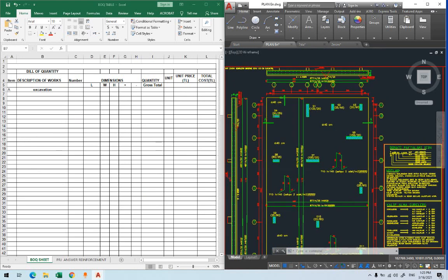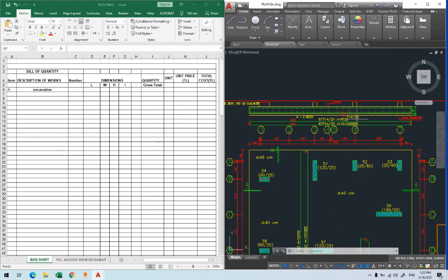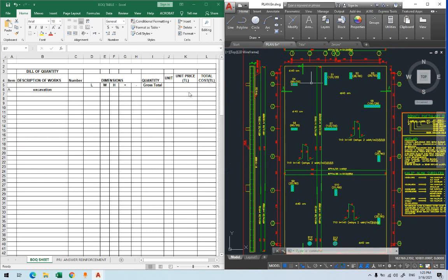So here we have a raft foundation. I already explained this one. We have only one excavation area here. We have mat foundation, or raft foundation. Now how many of this mat foundation do I have in this project? One. If I had 10 houses, I could just say times 10. Maybe it was a combined footing. We'll show you different types of this number, which we will call the repetitive. Do you have any similar mat foundation of this one? I only have one here, so 1.